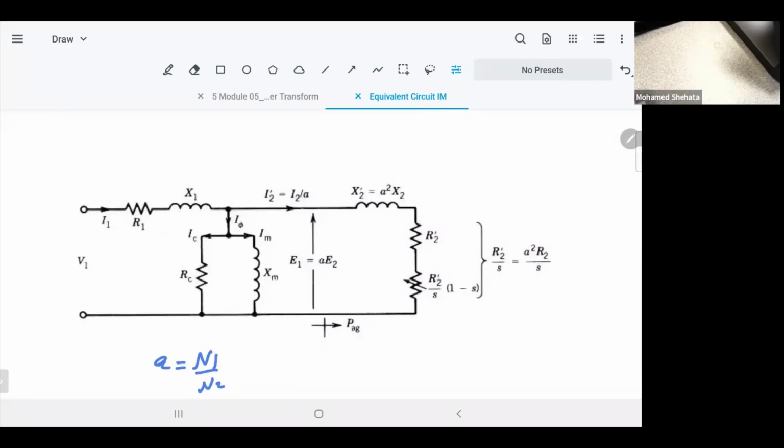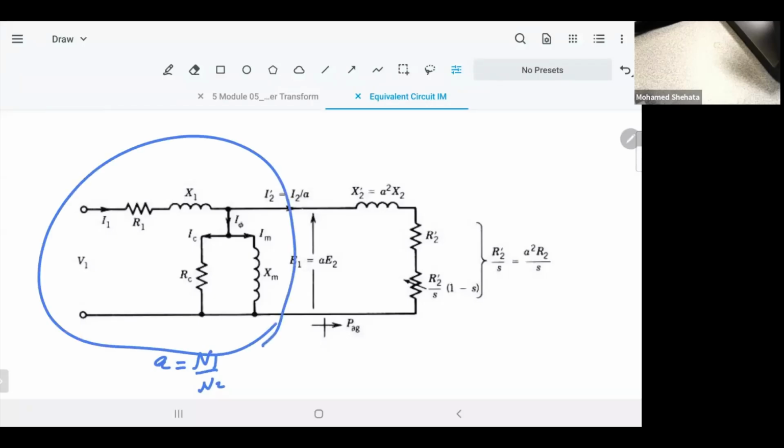So there is a guy with a theory that you study in circuits that can solve this. Thevenin and Norton. Great, that's good. I like this guy. It's solved, because simply, even if you don't know what is inside the circuit, you measure the open circuit voltage, measure the short circuit current, divide, and get the equivalent impedance. So what we're going to do is take this branch and find its equivalent Thevenin.